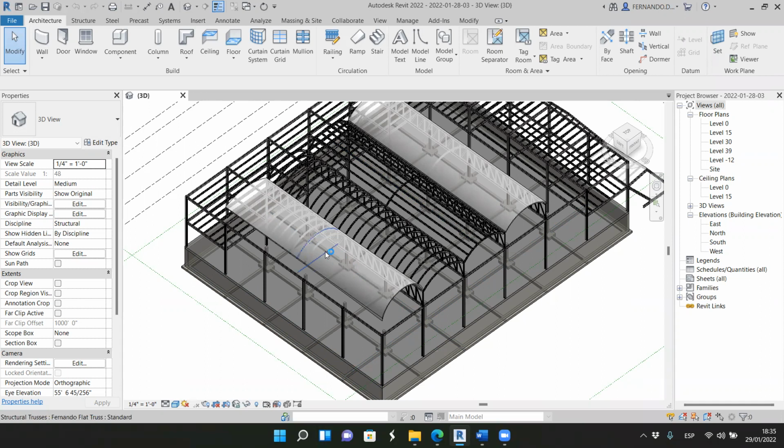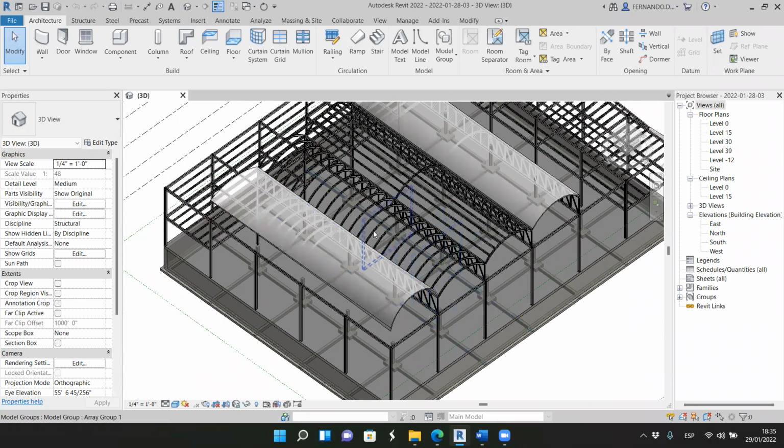It doesn't work if we are playing basketball or practicing any sports here. We don't need just sunlight in our eyes. So we need to cover this with louvers to protect the interior from the direct sunlight. A double skin can have this feature, and it's also a good way to save energy.